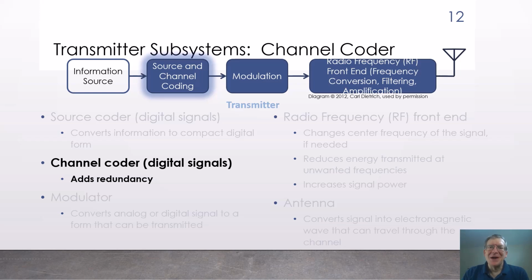Additional possible operations include interleaving, which shuffles the bits in a way that helps error correction work better in fading channels, and grouping of data into packets that can be routed and processed independently after reception.